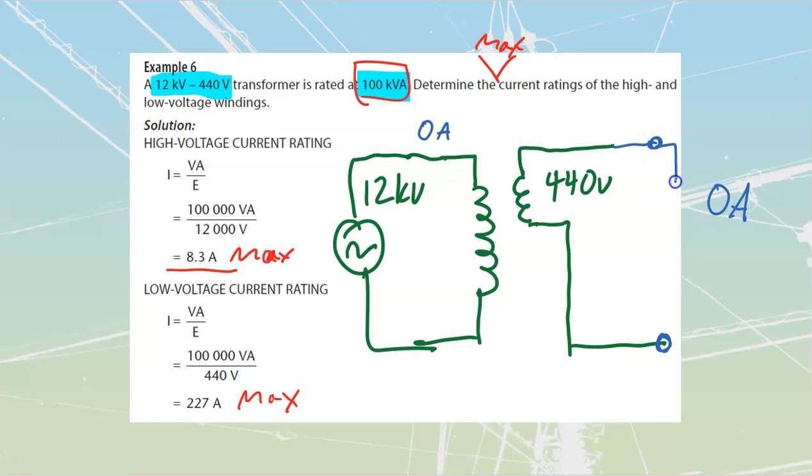Let's take a resistance and place that resistance across here. As soon as I place a resistance across here, is there a path for current flow? Well, yes, there is. Okay, how much current is going to flow? Well, we all say, well, I don't know. Tell me what the value of resistance is, and I'll calculate it for you. And I'm like, okay, fine, I will. Here's my value of resistance, 440 ohms, okay? So if I've got 440 ohms, I know that I can calculate my I. I is equal to E over top of R that I'm going to have over here.